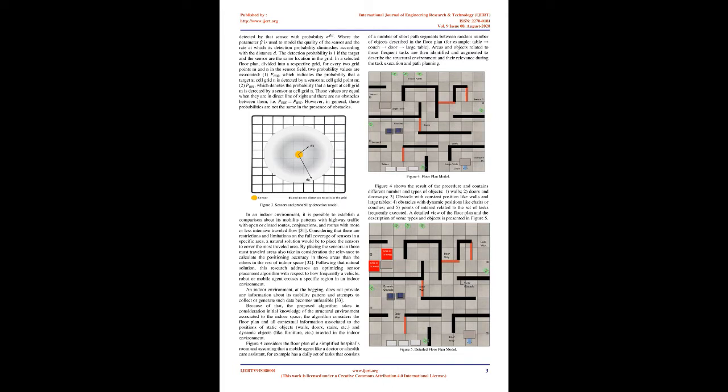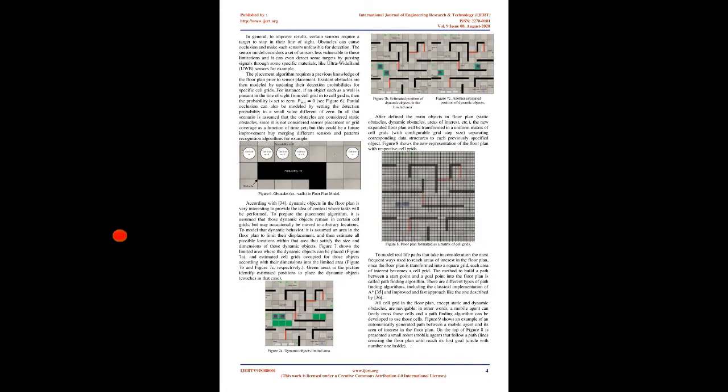The agent or object will provide statistical data that allow calculating the most useful or common route in the indoor environment. That statistical data or routes will be used as input data for the sensor placement optimization algorithm, which will take into consideration the agent's path to minimize the sensors' distance and maximize the signal transmission utilization. The following sections will present the methodology, mathematical modeling, and results obtained by using this proposed sensor placement optimization approach.